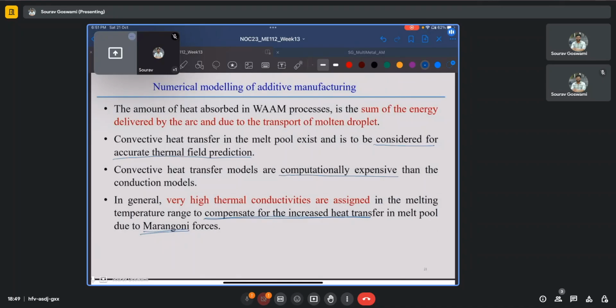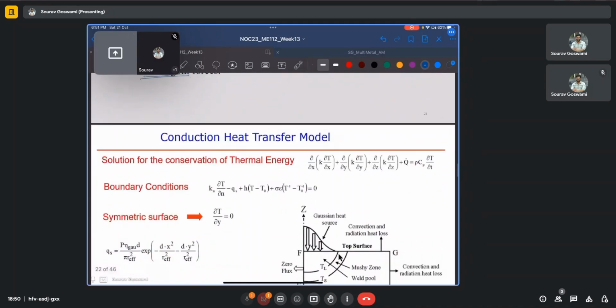The normal or natural convection, or the buoyancy driven flow, will have different characteristics, and it is actually the interplay between the Marangoni convection, the buoyancy driven flow, and the natural convection which finally decides the heat, temperature, and material distribution.